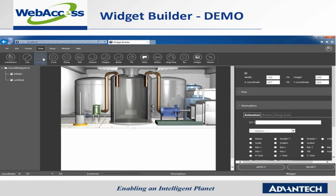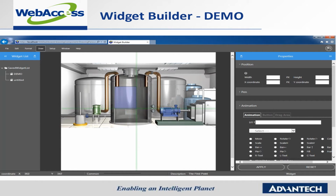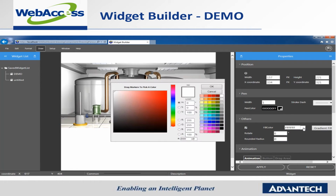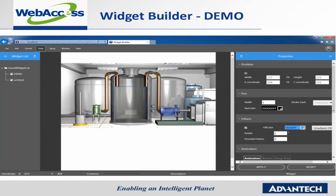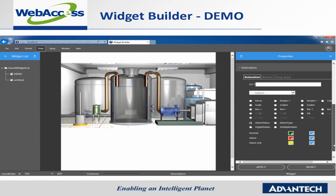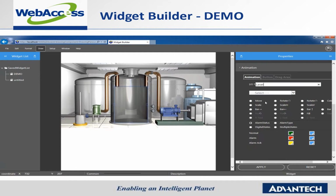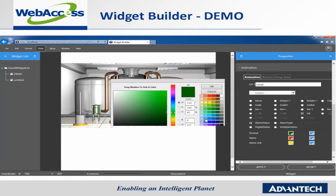Let's import the container's image as a background photo. And then we select a square in the painting tools. Drag the tool to form an area indicating liquid and select a color from the right for this area. Then we set up the test points and select an animation effect. Here we select Fill and complete setting of the liquid level.